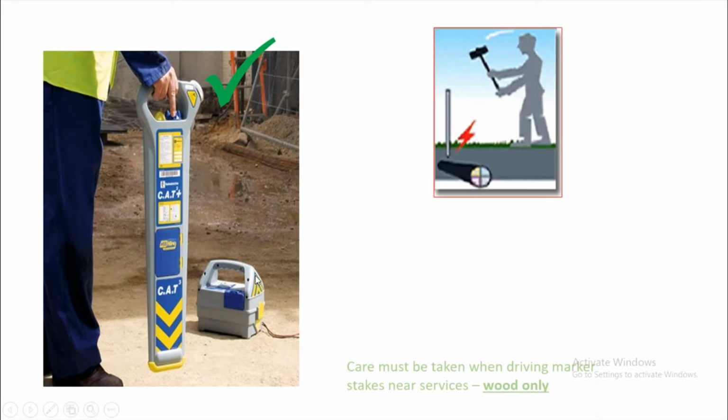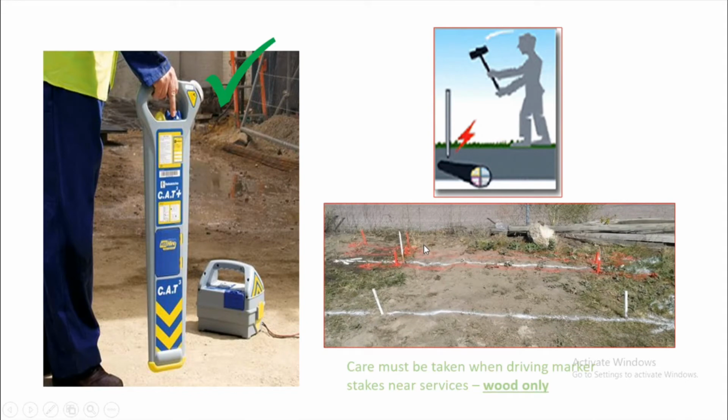So when you are doing penetration underground, you might hit the cable underneath. So be careful when using steel rods when you are doing it. We had one incident on site when they hit underground services of around 5 kilovolts. Imagine, it exploded immediately, and all the people at that location were shocked.